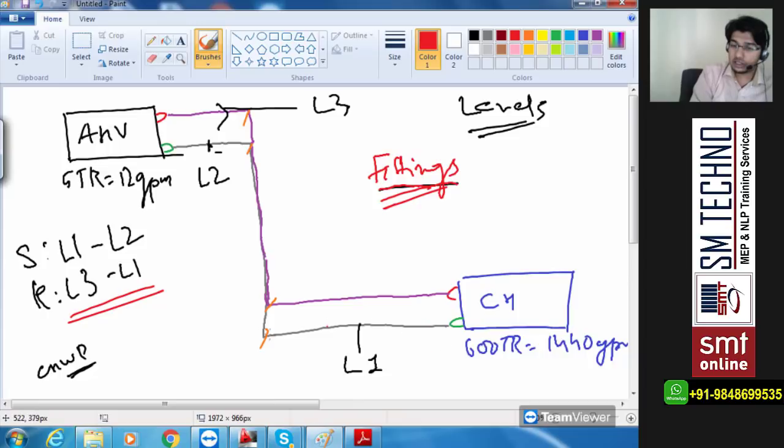Alright, because the water in the riser is going to take a turn and stay at the same level. So if the pipe is going to stay at the same level, just taking a turn, I can use a 90-degree elbow.